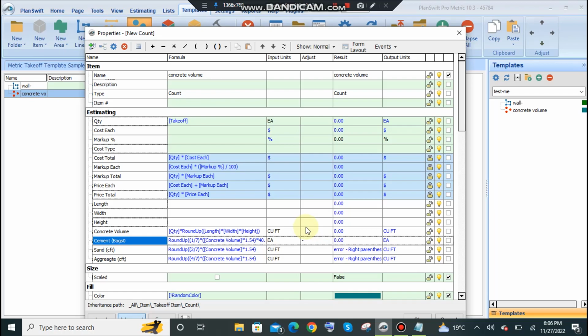So let's do it quickly to see how we can get results. Suppose these are our two similar columns. So let's open this command, click on this, and it will ask what will be the name of this command. This name will be okay for me. And put here the length of the column, which is in feet. Actually 9 inch in feet will be 0.75 feet, and width also 0.75 feet, and diameter 0, because this is not a circular column. Actually if there is a circular column, then you will get some value here.